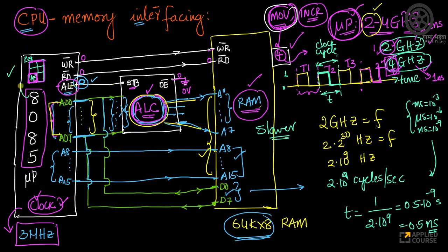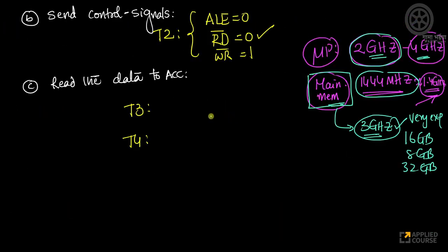That's why accessing data from your registers is faster than accessing data from the RAM. Right? Because registers are operating at the same clock speed as your microprocessor itself. You can actually access registers at the clock speed of the microprocessor, but the RAM itself is slower. So whenever, till now we have been saying, right, accessing data from the RAM is slower than accessing data from the registers. Why is it so? Because RAM's internal clock at which they operate is slower than the clock speed of microprocessors in most real world applications.